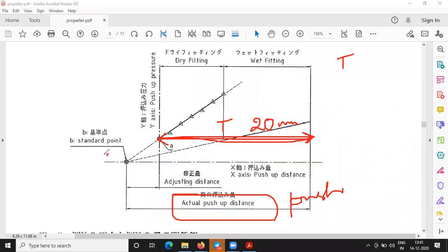It's a virtual point, but earlier initially you had given 50 bar and you adjusted the dial gauge to 0. Okay, so the dial gauge might have already shown a deflection of 10, it might have shown a deflection of 15, 20, but what you are doing, you are making it 0. So you don't know what deflection the dial gauge has made.